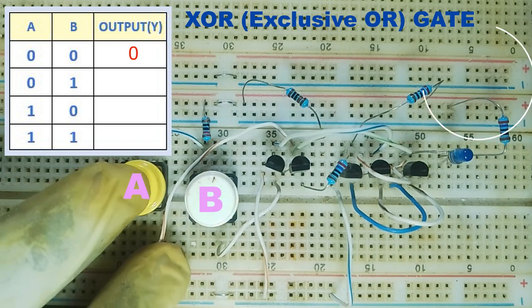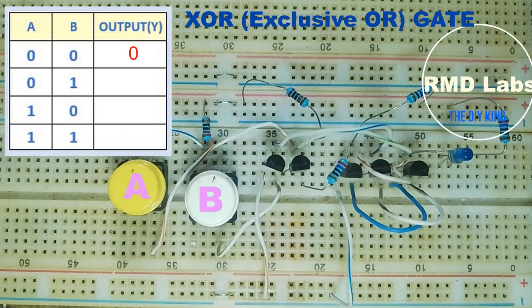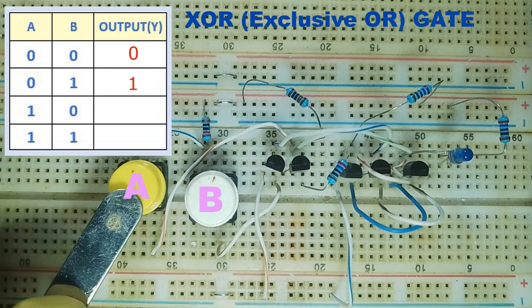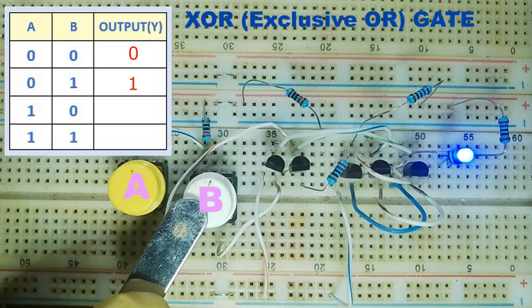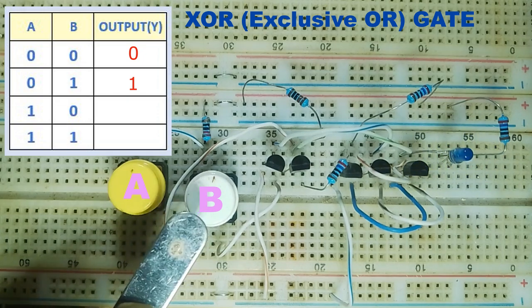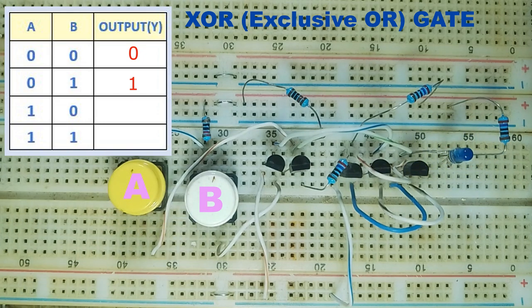Both inputs A and B are at logic 0, and noticeably, the output is also at logic 0. That is the first state. Pressing input B to drive it high turns on the LED, a logic 1 at the output. Doing the same with input A gives the same result. Let's fill them up in our truth table.